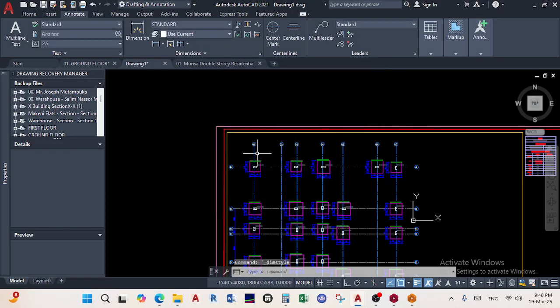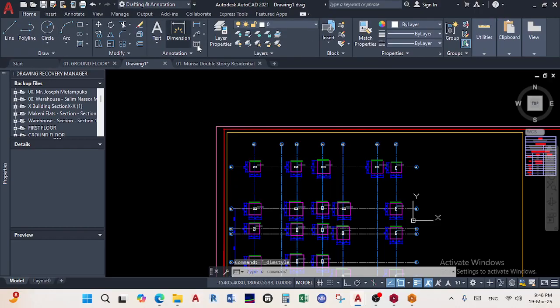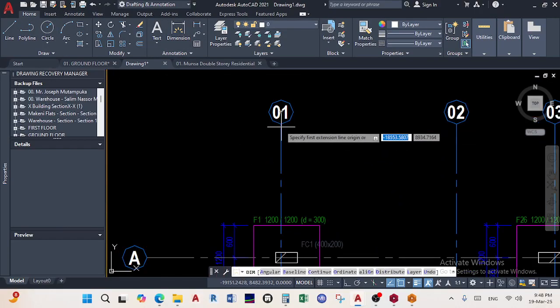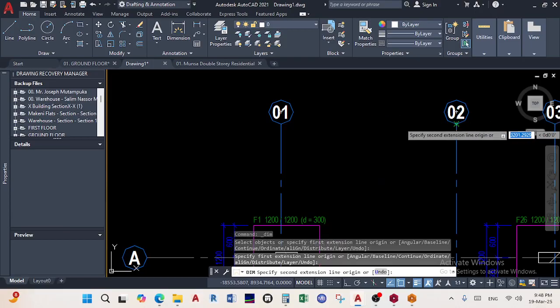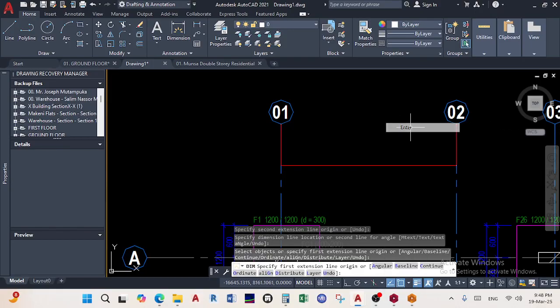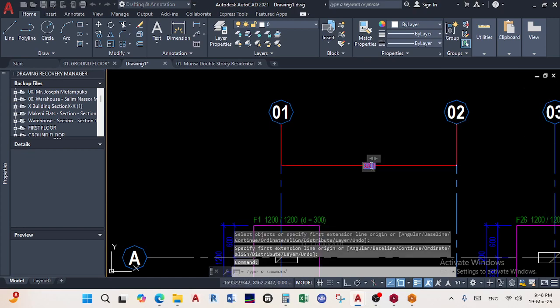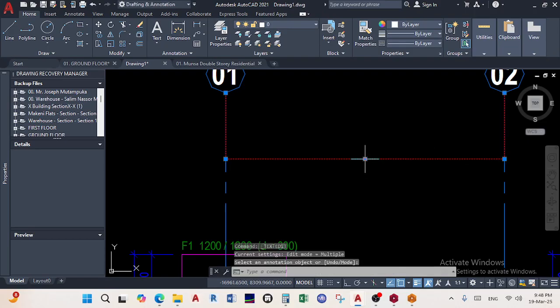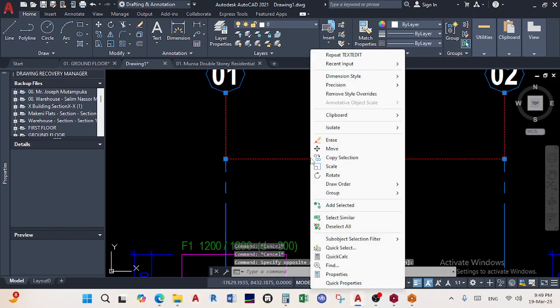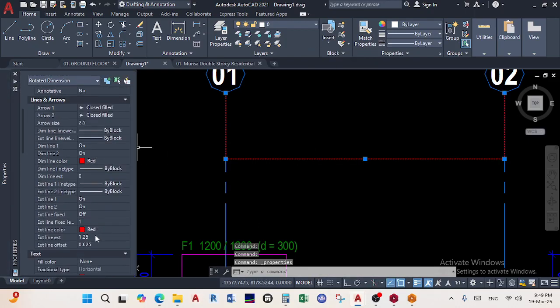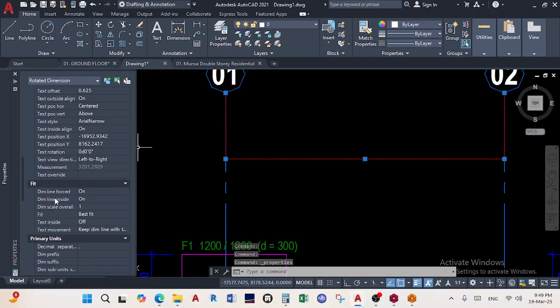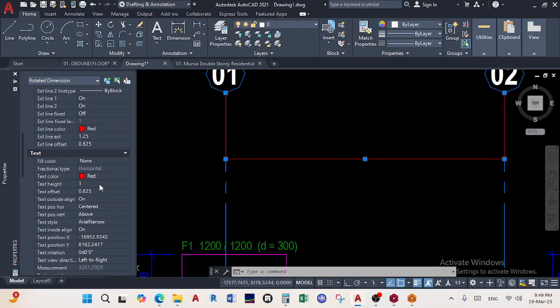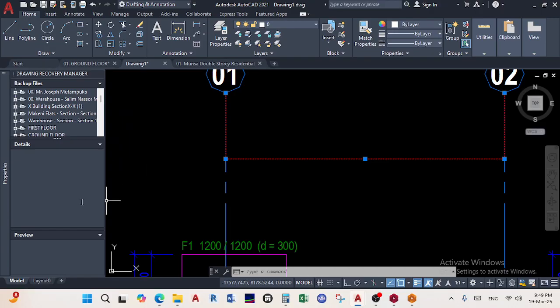Since I had forgone dimensioning in project details, I'll now dimension in AutoCAD like that to there, like that. I know already that my text is small. If I double click, I can see it there, but I know it's small. So what I can do is I can right click, go to properties. I can change the properties of this dimension. The text section there says it's 1. I do not want the text to be 1. I want it to maybe match this one at the top.